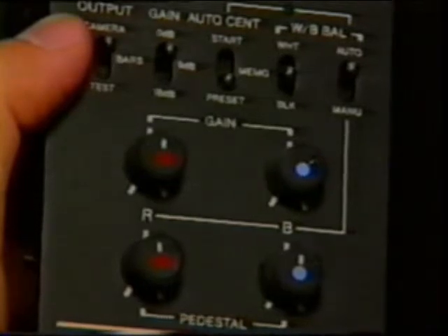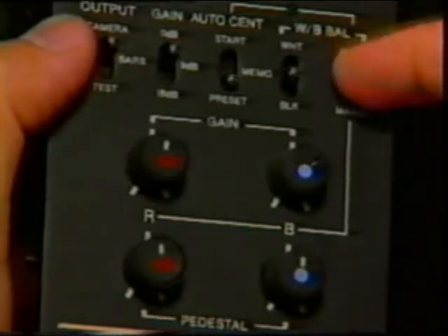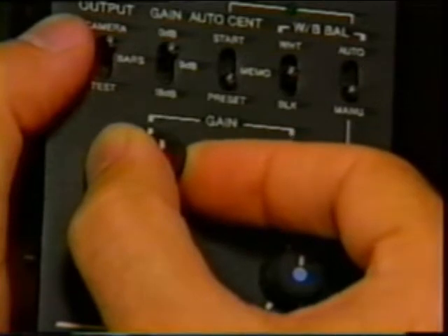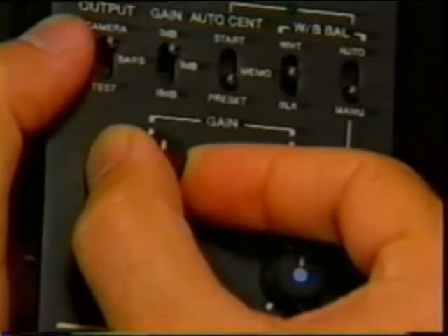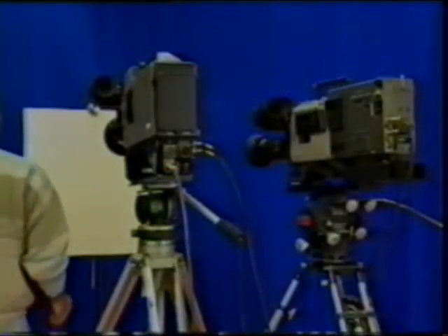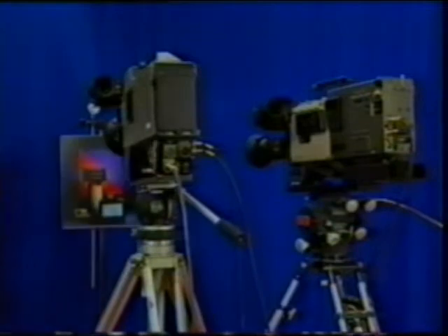To fix this problem, you must go back to the original source and adjust the blue, or in this case, the red gain on the camera control unit. It's a good idea to never touch the green control. This can create major color balance problems. Adjust these controls until the fuzzy spot is at the graticule's center. Once you've used the Vectorscope to match both cameras, you can pull the cards and fine-tune colors of the scene.